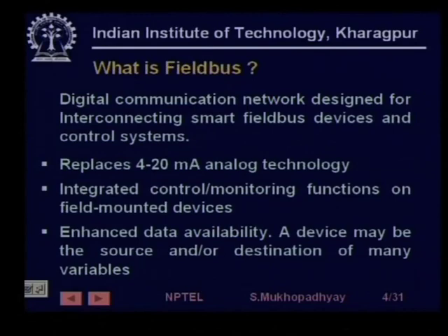So, all the signals had to be carried away to the central computer, incurring very large wiring and making the data noise prone. These defects will be removed if we can have some intelligence on the field mounted devices. So, that some abstract command signals will come, and the low level control signals, where the feedback is taken and the controller actually generates the output, can be computed on the device itself.